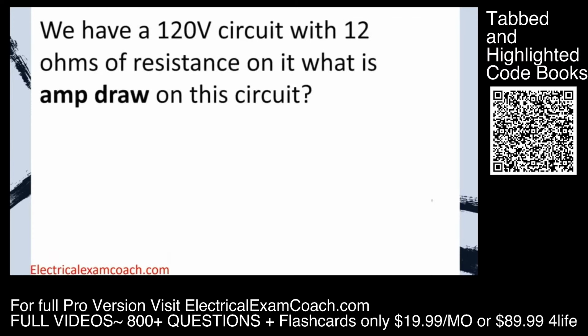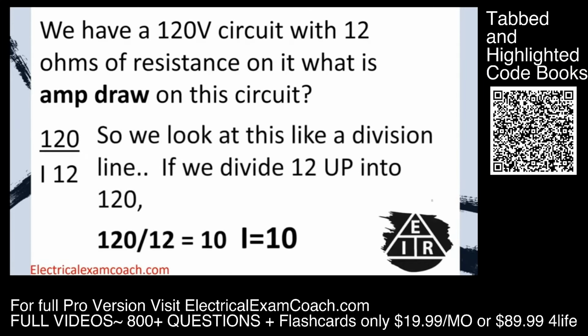In this case, we have a 120 volt circuit with 12 ohms of resistance. What is the amp draw on this circuit? Well, what I love about formulas is we just plug in what we know. We know we have 120 volts. We know that we have 12 ohms of resistance. And we're going to look at this like a division line. We just take 12 and divide up into 120. We set it up like this. 120 divided by 12 equals 10. That lets us know that there should be 10 amps of current on this circuit.